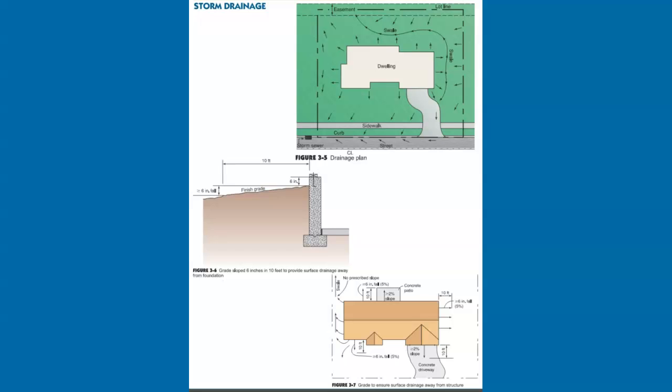The prescribed slopes as previously discussed are concerned with the first 10 feet away from the structure. The IRC also has requirements for drainage to an approved location such as a storm drain, storm sewer inlet, or the street gutter that leads to a storm drain. The drainage design must consider the entire lot for any impediments to drainage during heavy rains. Ref. R 401.3, flood